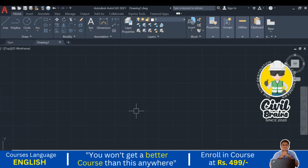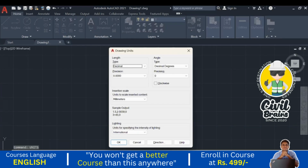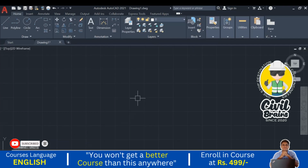How to set the units? Go to the command prompt, type units and press enter. Here you keep it as decimal only. Precision I will keep 0.00, and here it is millimeters. Press OK, and the units are set. So what is the next step?